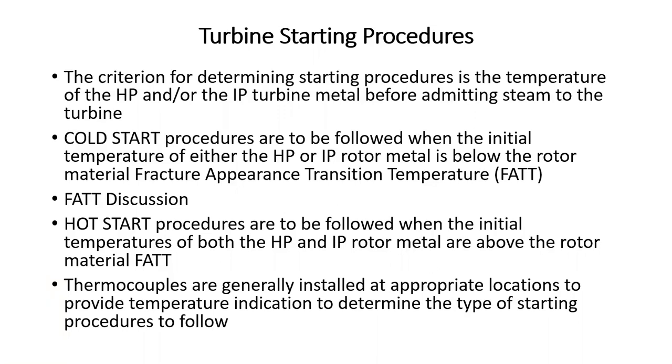That ductile to brittle transition temperature is what we call in the power industry the fracture appearance transition temperature. The way they talk about it in the power industry literature is they break those Charpy impact specimens at different temperatures, and then they take a microscope and examine the fracture surfaces. And the temperature at which the fracture surface is about half cup and cone and about half cleavage. The cup and cone is what they call the ductile fracture.